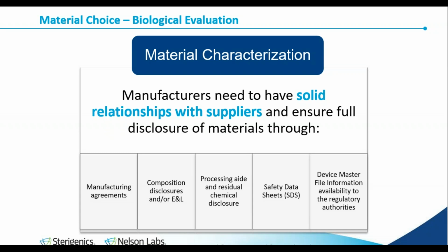Specifically, pharmaceutical type products can be very prone to something that might be a simple change from a supplier standpoint, like location, maybe their supplier for the resin, or subtle changes in processing can make a significant difference in an extractable or leachable material. So having those agreements with really strict change control is critical.